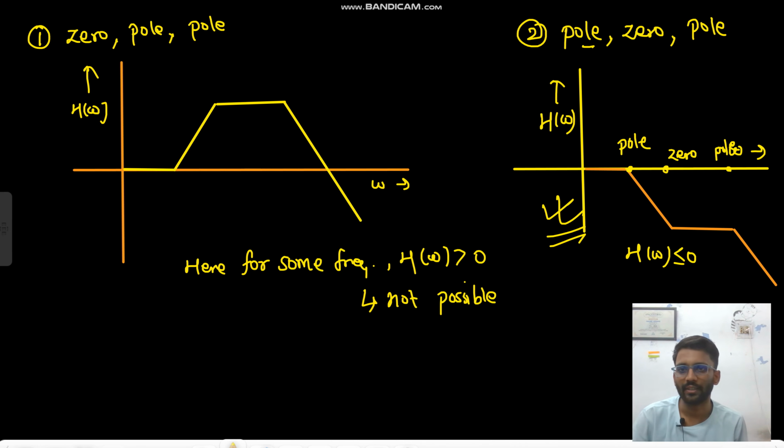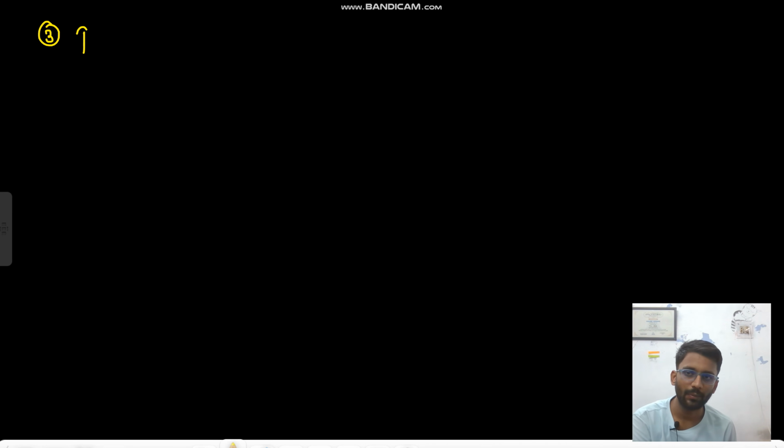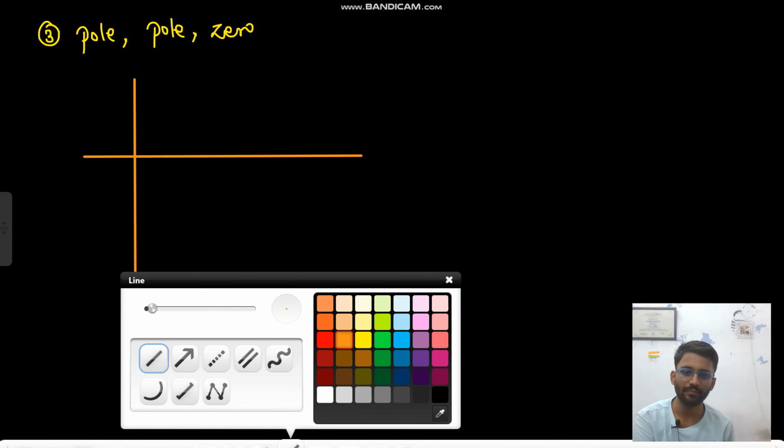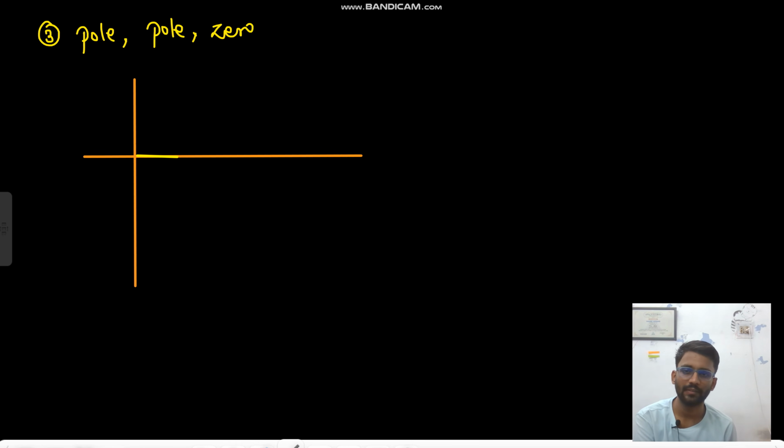And let us see if other conditions are possible or not. We have taken zero, pole, pole, and pole, zero, pole. Now more condition we can take is pole, pole, zero. That condition we can take, right? First DC, then minus 20, then minus 40, then again minus 20, right?